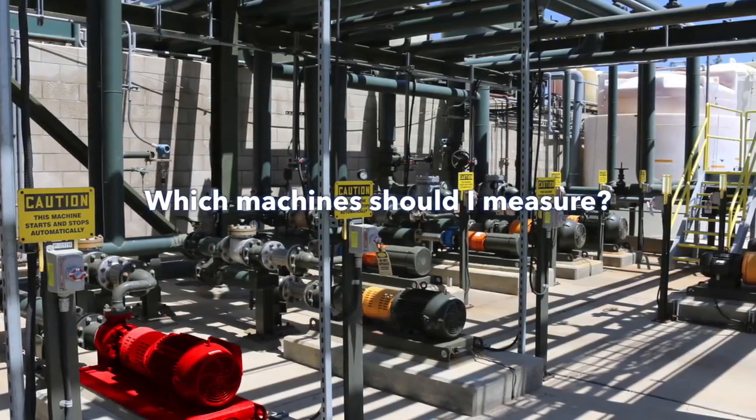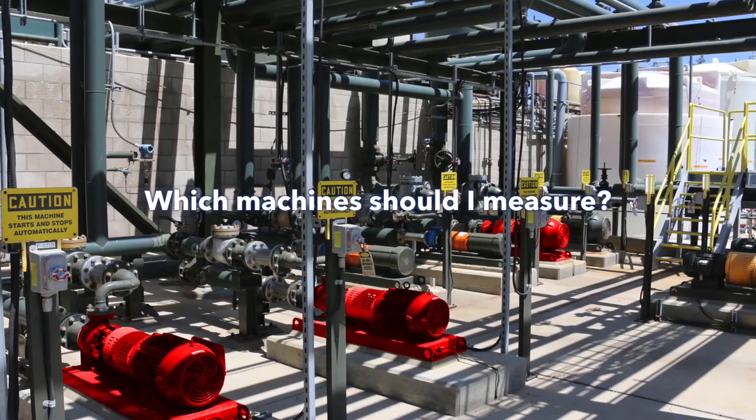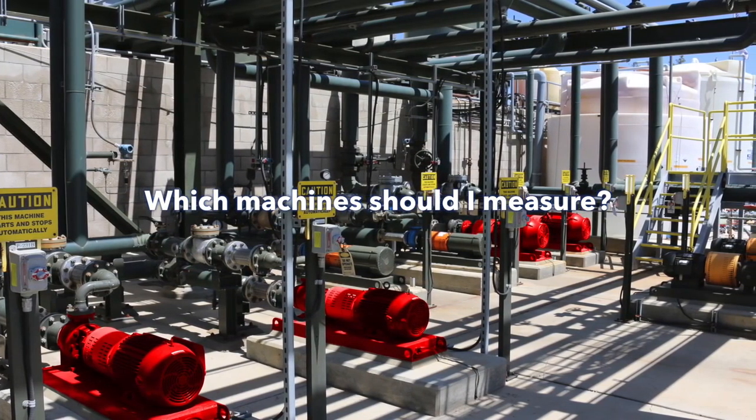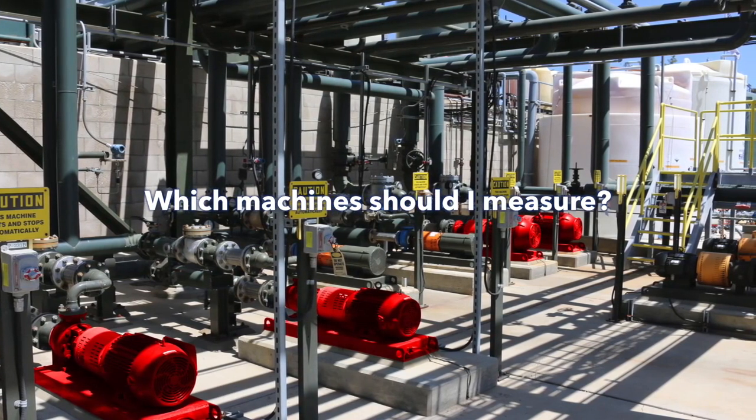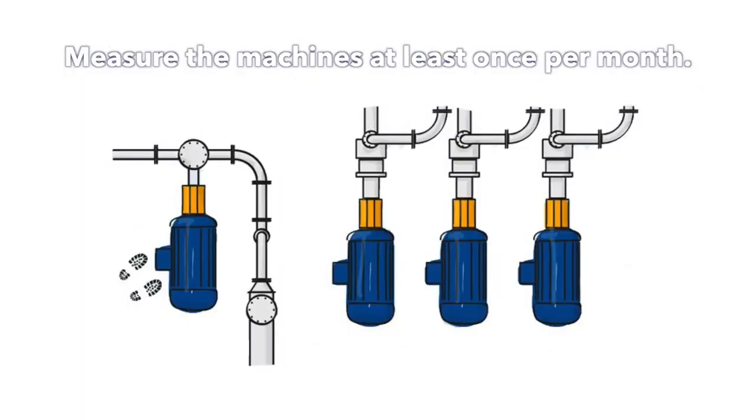You need to consider which machines are critical for your factory's production. These critical machines should have the greatest priority over the other machinery, and you should also consider how much time you can spend on measuring them regularly. It is ideal to measure the machines every week, but we're not living in an ideal world. Despite that, try to schedule measurement of those particular machines at least once a month.